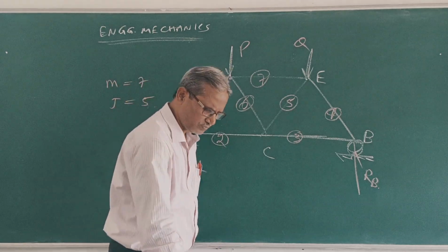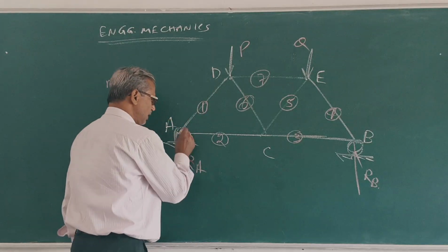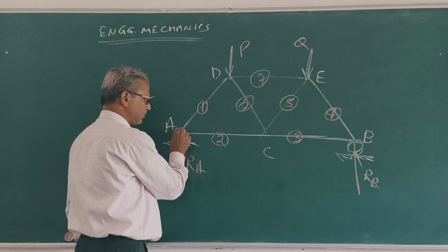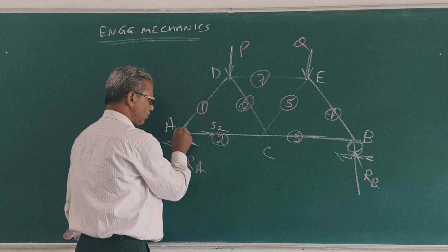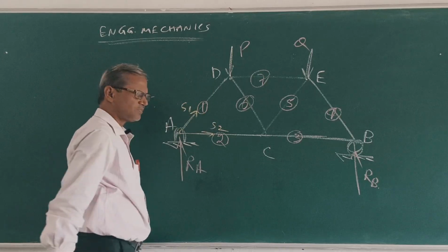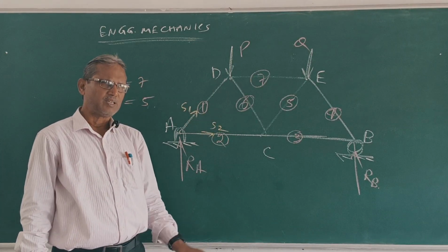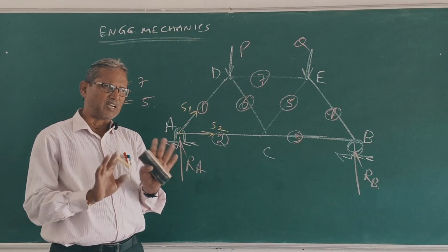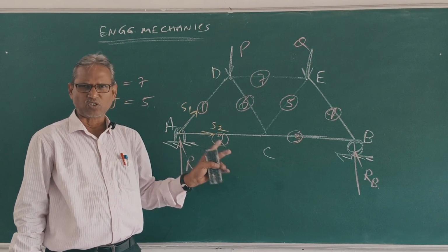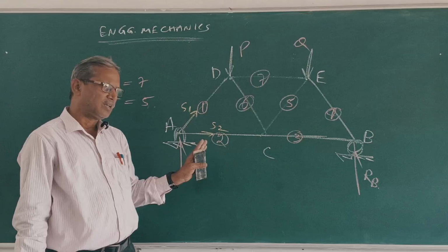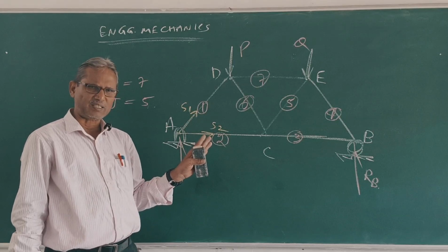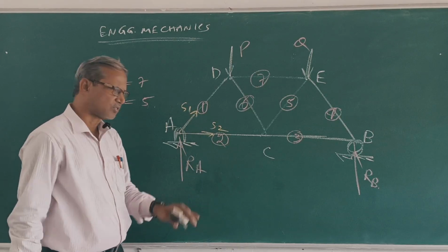What is two force? Suppose I start from this joint. So this is force S2, this is force S1. Give the direction of each force in the outward direction. If the answer is positive, it is tensile force; negative, compressive force. So mark all the directions at each joint in all members.